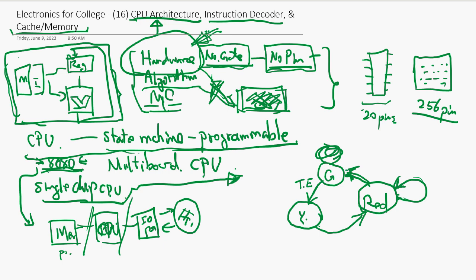Only if you push the button does the signal start changing for pedestrians to start walking. So this condition becomes pushing the button. Then it goes through the cycle again, comes back and stays there in red. So the timer expires, it goes back to the beginning, and keeps repeating until somebody pushes the button.